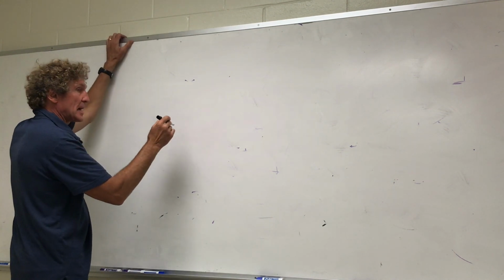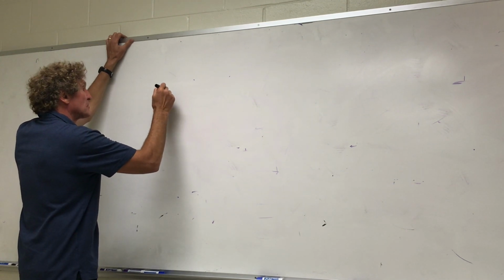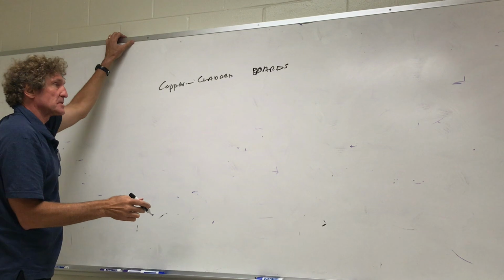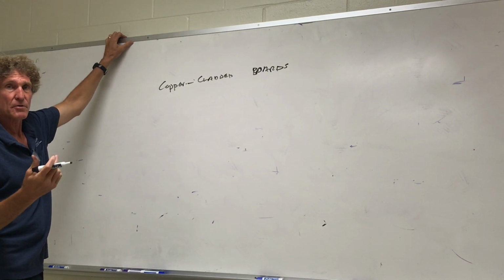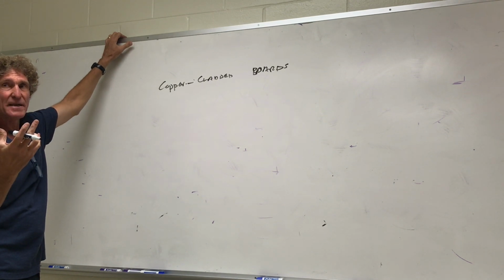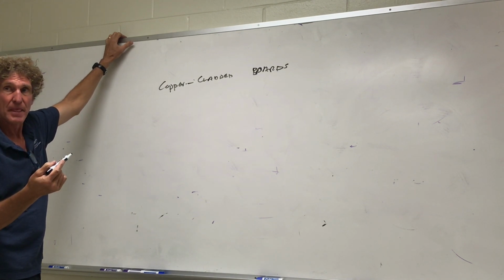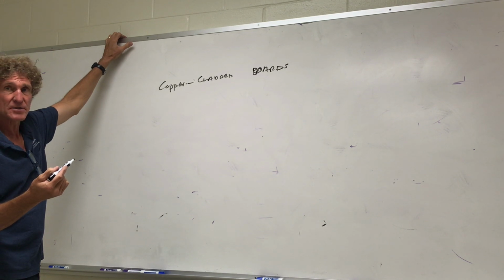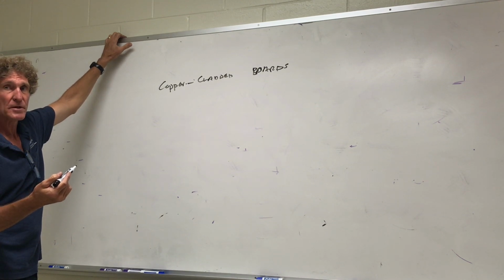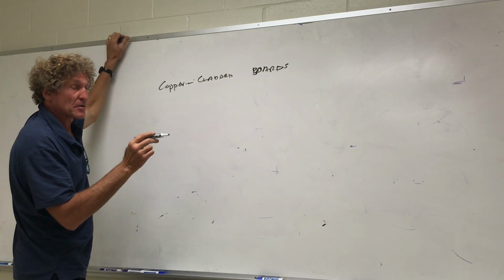So here's what typically happens. You're going to have something called Duroid board, or a high frequency laminate. You don't have to worry about this, but this is copper clad board. Sometimes it's only a single layer of copper. Do you know what FR4 board is, the green board? If you ever rip apart routers, stuff like this, low frequency routers, you'll see a green board with a whole bunch of things soldered on the back of it. That's called FR4 board. That's very lossy. You can use it, but not at high frequencies. Usually they use something called Duroid board, a high frequency laminate, and the reason they use it is because there are lower losses.